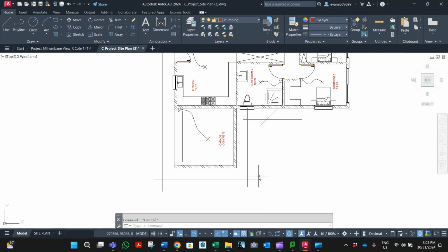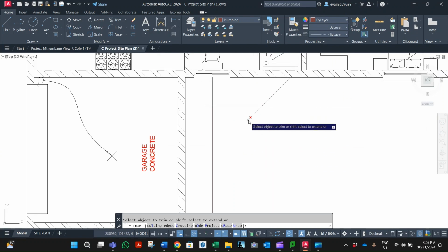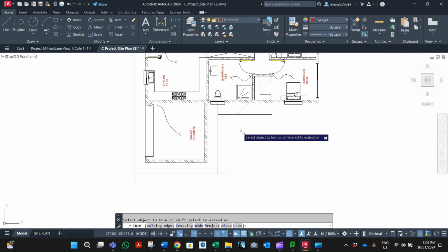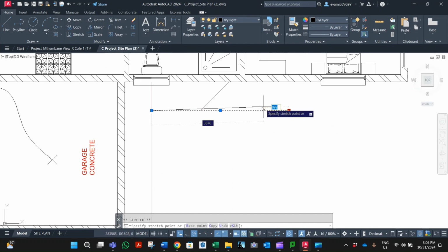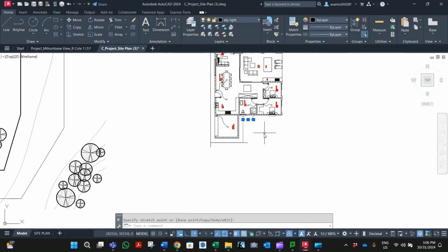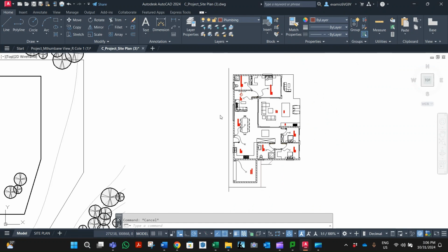We're going to trim the following. I'm going to trim there and I'm going to trim there. When I turn a corner, I'm always going to leave a little bit of an extension for a rodding eye. Now, it doesn't always have to have that. I'm going to bring inspection chambers as well. I'm going to pull that in a little bit to there. We don't need the rodding eye extended too far beyond those turns.